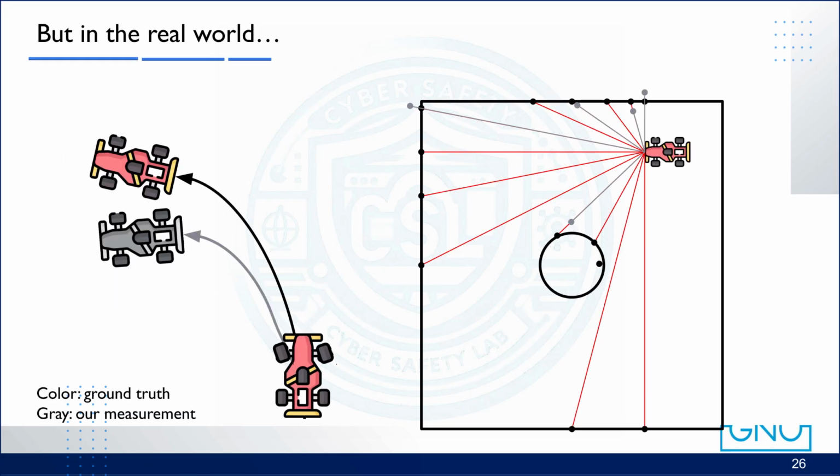In the real world, odometry is far from perfect. Wheel slip, motor RPM errors, and small control inaccuracies accumulate over time, causing the robot's estimated pose to drift away from the true pose. LiDAR scans are also noisy, with small errors in each range measurement. As a result, the perfect map-building approach breaks down once uncertainty enters the system.